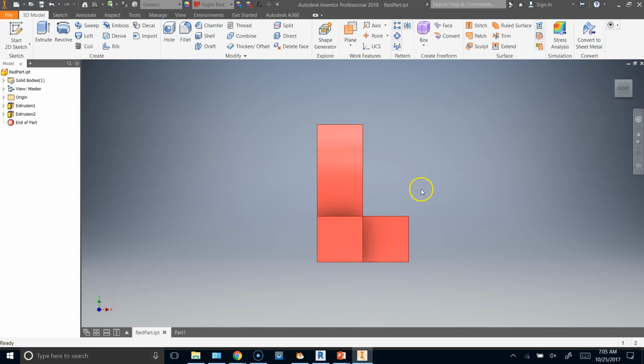And I often use my front view as the starting point for my sketches because I see an L shape. It's 2 cubes wide, so it's 1.5 inches in this direction. It's 3 cubes high, so it's 2.25 inches in this direction for the height. And the depth isn't something I'm going to worry about necessarily because, well, a sketch is just two-dimensional, and all I'm going to see is an L shape. So this is what I'm going to use for my first sketch.